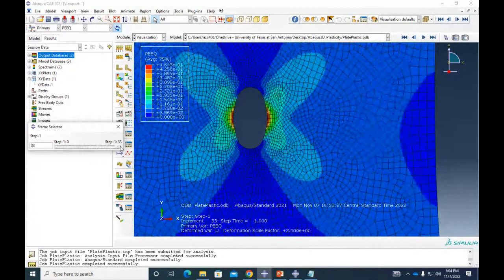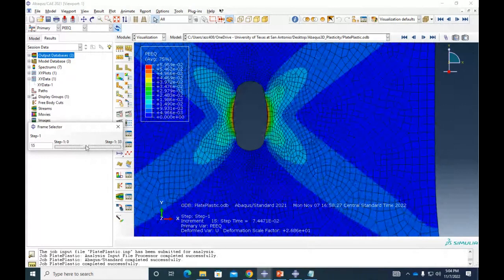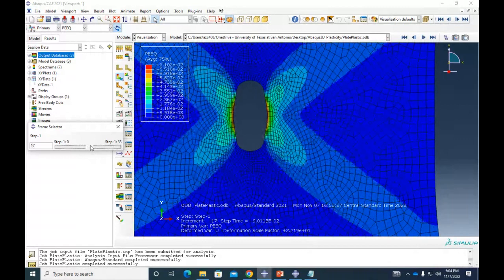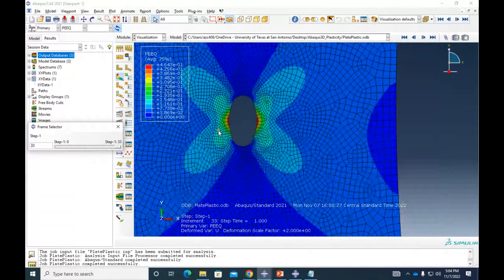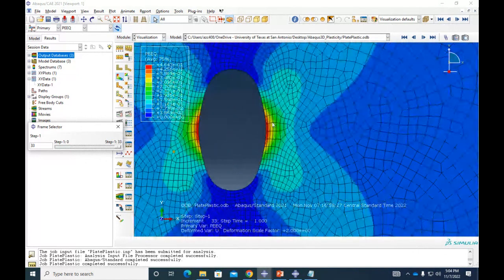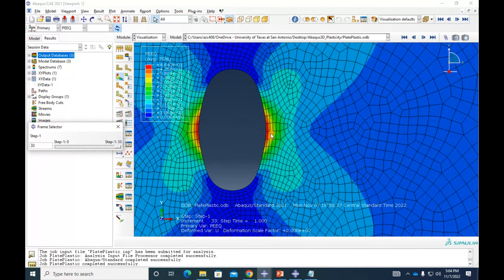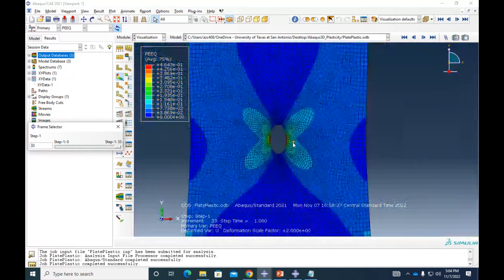Eventually, you see this point where it went from being expanded to going back. At that point is where fracture should happen, but we don't have fracture in this problem. So whenever we reach a certain amount of plastic deformation, we are going to say, hey, that element undergoing a lot of plastic deformation, just remove it from the mesh. It's not useful anymore. It's no longer capable of holding load. And that's how we start doing the crack propagation. Interesting? Yeah.